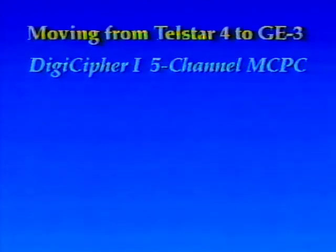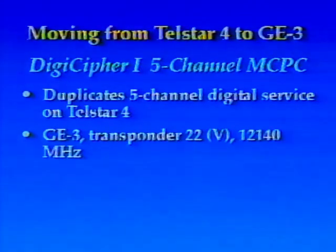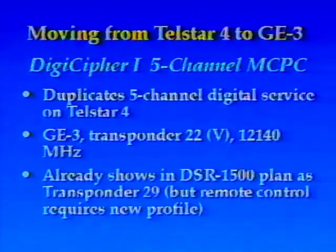Let's talk about the specifics of moving from Telstar 4 to GE3, and in particular the specifics of moving to the Digicipher I 5-channel MCPC. It will exactly duplicate the 5-channel digital service that you're currently getting on Telstar 4, composed of schedules 5A0, 5A5, 5B1, 5B5, and 5B6. It's an exact match, except that it's on a different satellite. It's on GE3, transponder 22, vertically polarized at 12140 megahertz. And it already shows in your DSR 1500 plan, if you haven't changed it since that very first time we told you what frequencies to load in that plan when we were on Telstar 4. For remote control users, it does require a new profile. We'll talk about that a little later in the video conference.